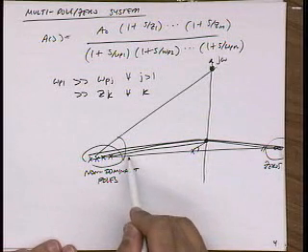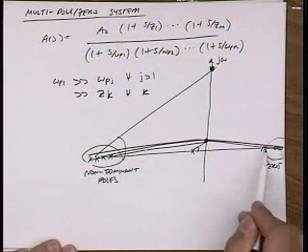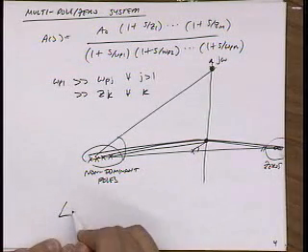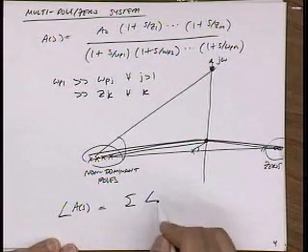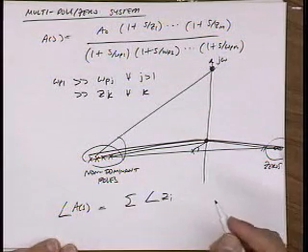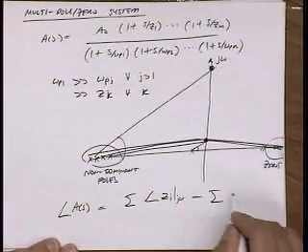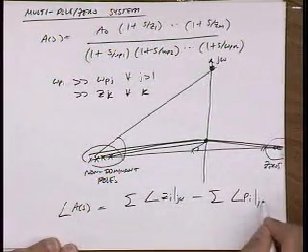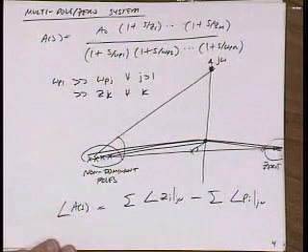About half a degree, 1 degree, right? Same with the zeros. They're contributing very little. Because the phase of A of S is basically the sum of the phase of the zeros measured relative to the j omega axis minus the sum of the phase of the poles relative to the j omega axis, right? So this is the angle relative to the j omega axis.